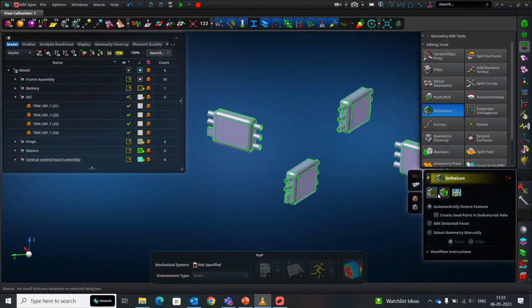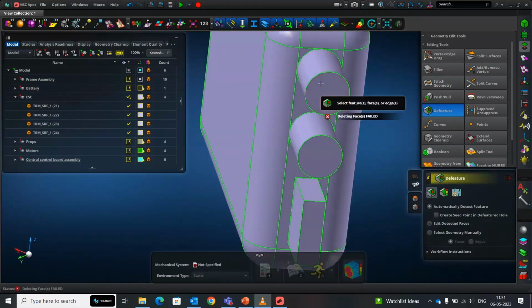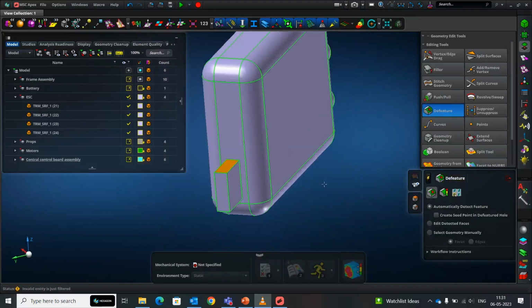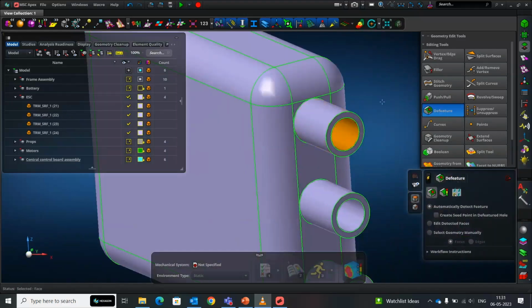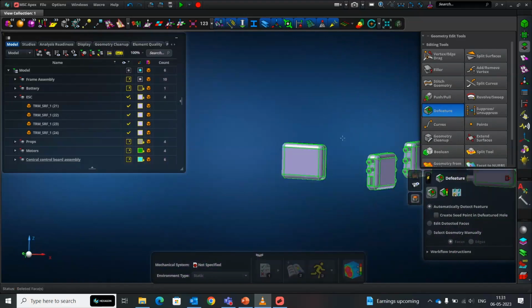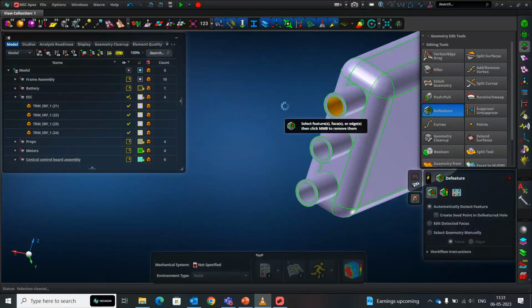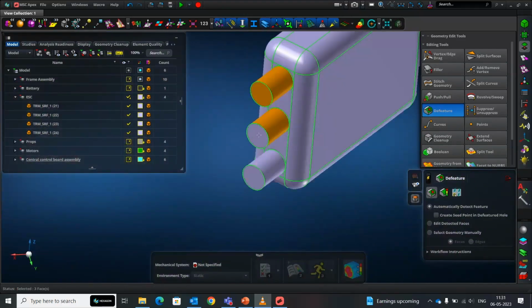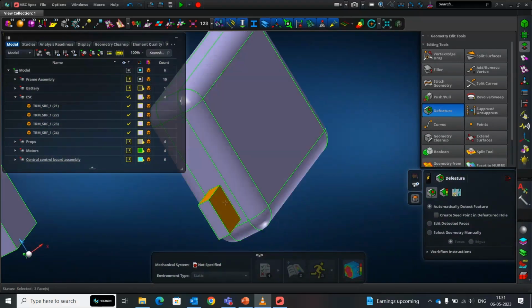And then I also have what is known as defeaturing. Defeaturing can be done based on the faces and also the features. So you can see I'm going to be defeaturing this by selecting unwanted faces and then eliminating that aspect itself. So whatever you see as a cable sleeve and things like that, which are insignificant for this analysis, I'm going to eliminate. I can also eliminate the fillets that are given there because I simply need the block structure for this. And in fact, I'm not even going to utilize this for my analysis because I will soon show you what the benefit for this is.